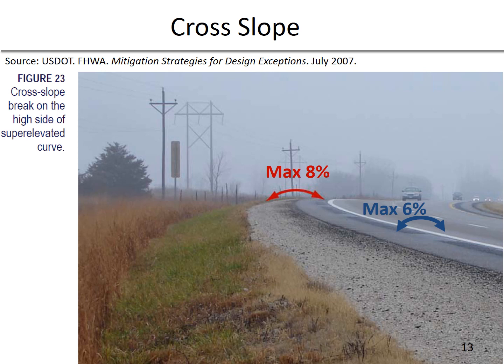On high-speed roadways, the normal cross slope is between 1.5 and 2%, with a cross slope break, which is the algebraic difference in the slopes between the lanes, at the center line not exceeding 4% in areas of intense rainfall and where there are 3 or more lanes in each direction. Additional cross slope may be necessary for adequate drainage. Accomplishing other design features like superelevation transitions and pavement warping at intersections will inevitably require removal of cross slope in spot locations. These cases are routine and necessary in design, and a design exception is not required in those cases.